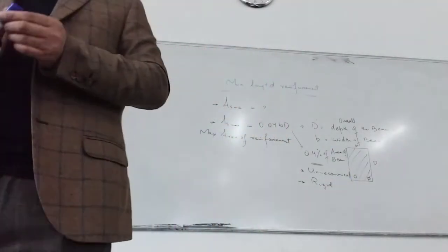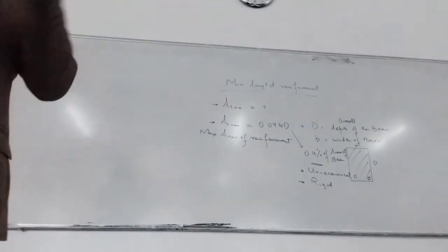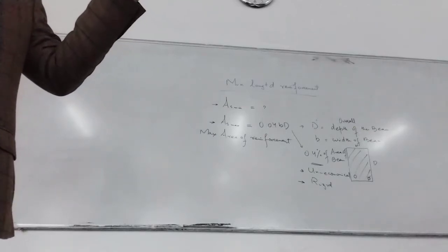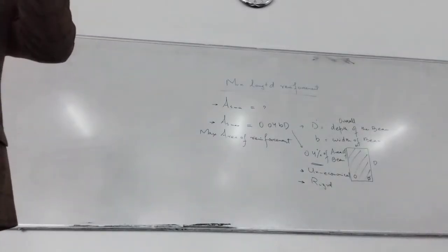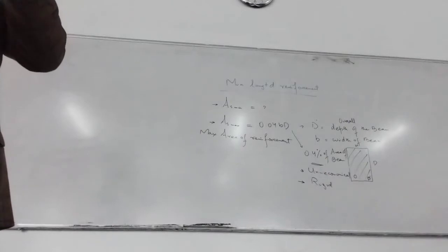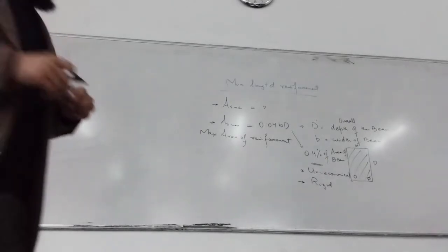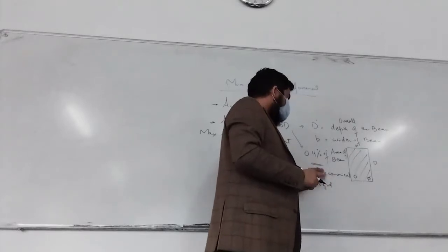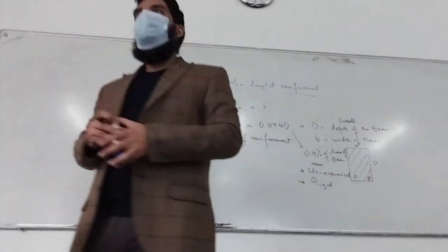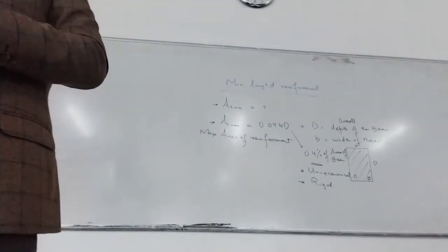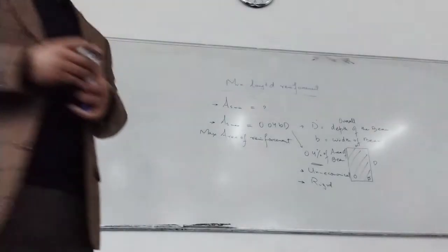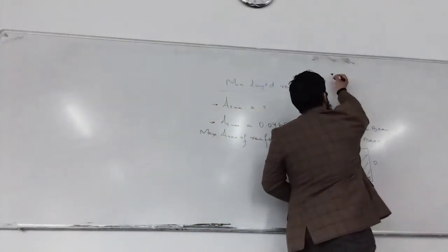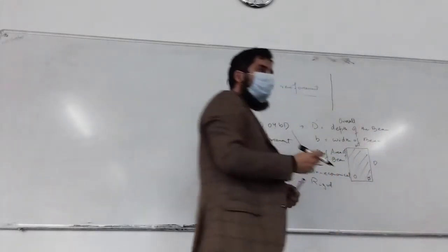The more steel you have, the more rigid it is. Ductility is that it can stretch out while going towards failure, but rigidity is its rigid behavior. It becomes more rigid if you keep on increasing the area of steel. So now we have a limit to the maximum amount of reinforcement in beams, as well as in slabs, or we can say for flexural sections.